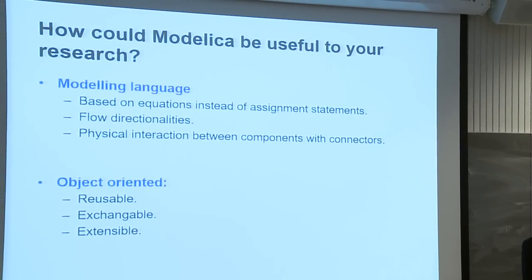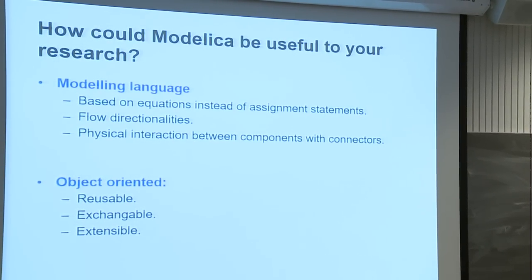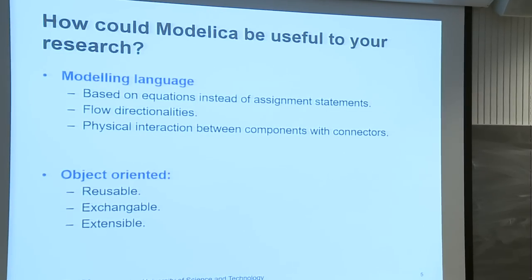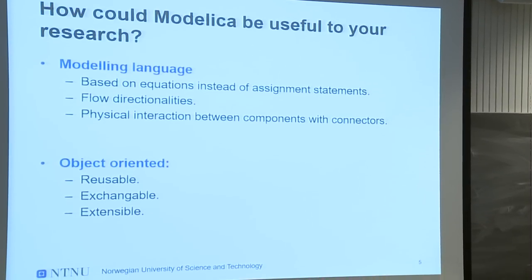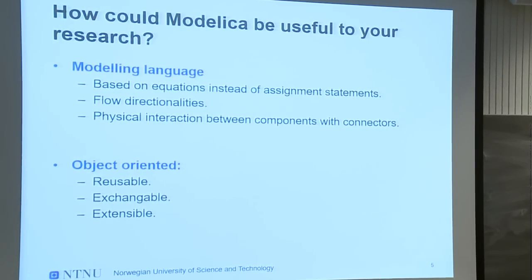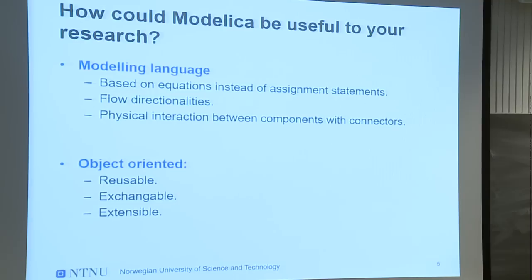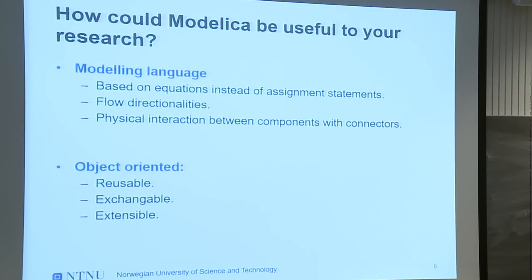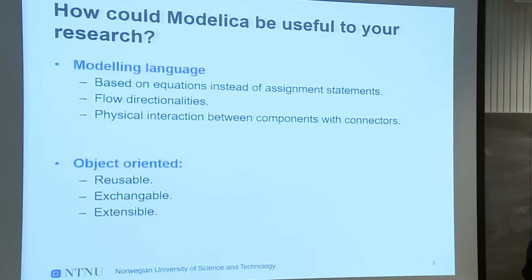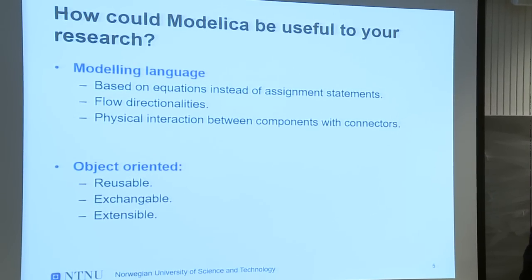And with the nice word extensible, you can just build up hierarchies. So the basic stock, for example, like a pressure drop equation, which is always the same for a heat exchanger or a valve or a reactor, is something you only have to code once, and then you can load it in each of your different models. So that is meant with extensible, which is a kind of hierarchic level of the Modelica language.